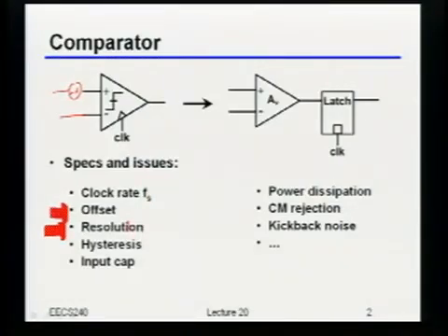As we'll talk about probably not this time, but maybe next time, there's another very interesting thing that tends to happen in comparators, which is they tend to remember their previous decisions. Sometimes if you happen to get a 1 last time, it'll be harder for you to flip the value of the comparator and get a 0 this time. In fact, sometimes you can even have so-called negative hysteresis, where if you had a 1 this time, it really wants to be a 0 next time.